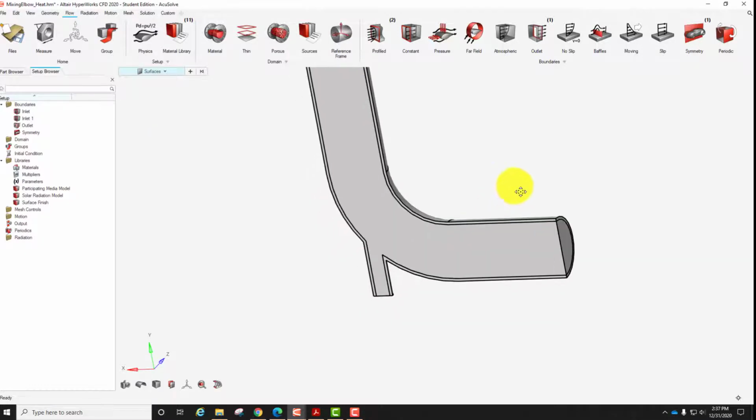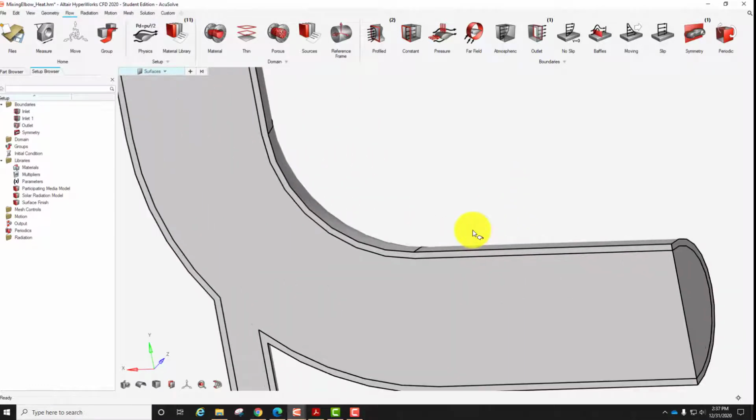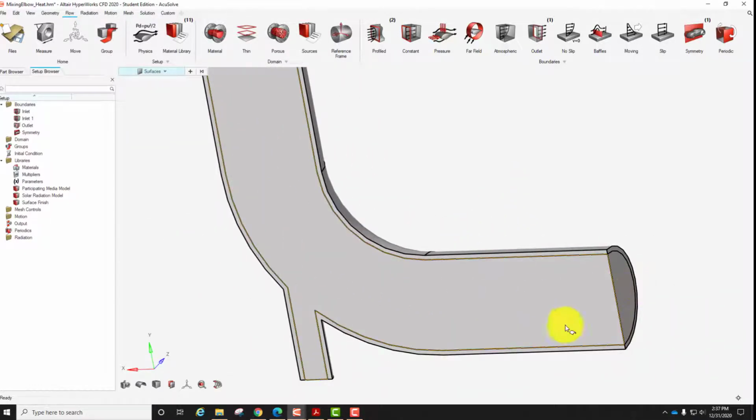And then for the thermal analysis, since this is fluid flow and we also have solid steel here, you need to define the pipe wall or steel wall symmetry. Before, this symmetry was for the fluid, but you need to define the thicker wall for the symmetry.